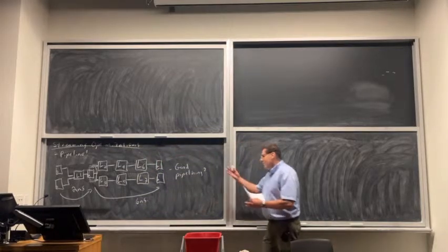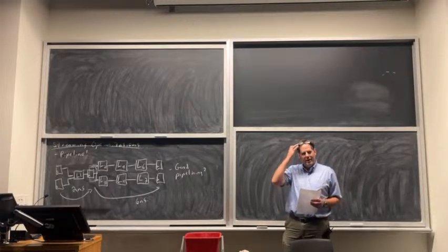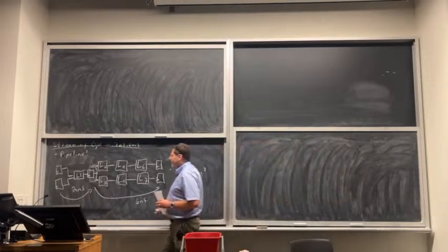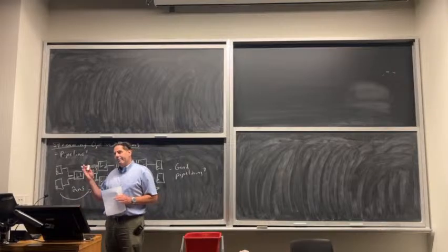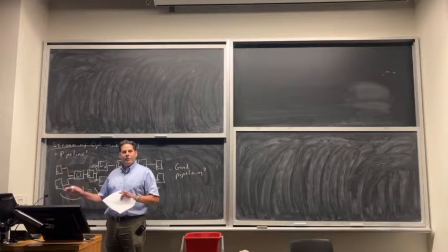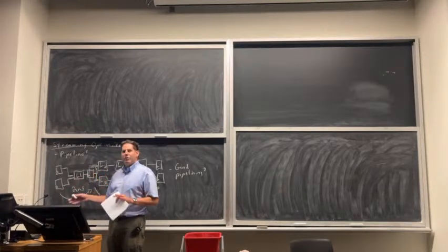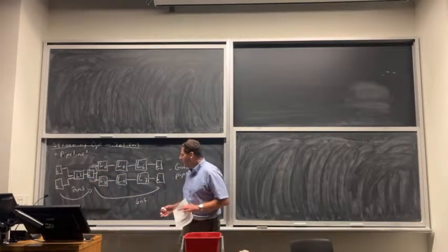So does anybody know of an automatic optimization that could help us with this? This is something that CAD tools can help with. So do you know the name of the algorithm that can help you with this? CAD tools can't actually pipeline your design automatically because they're changing the latency, and that might not be okay, except with a bunch of restrictions on the design style. If you make enough restrictions on the design style, then a CAD tool could pipeline it. But in general design styles, a CAD tool can't actually change your pipelining. A human needs to go in and do it.